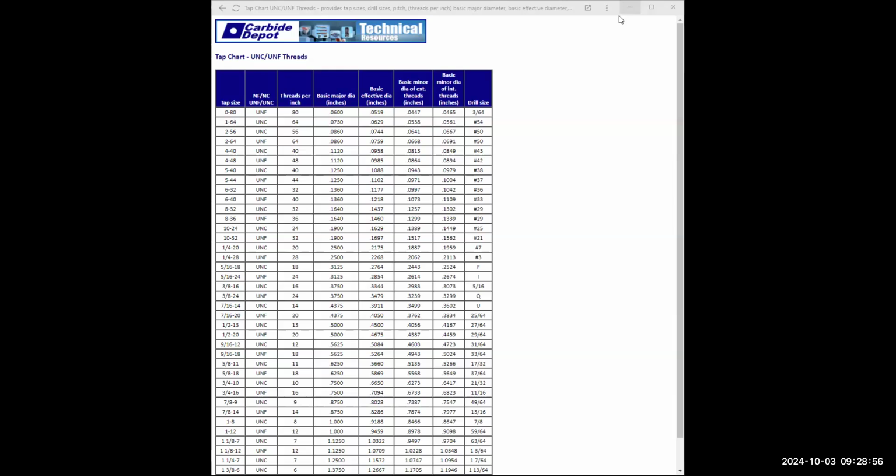All right, now, the other day I showed you chain dimensioning. Today I'm going to show you datum. It's a little bit different. Click here, look. Click here, here. I'm trying to keep the spacing consistent. This is more accurate when you machine this. I would prefer to have these dimensions in the top view, but since I have so many notes up there, it would be a headache trying to do that.